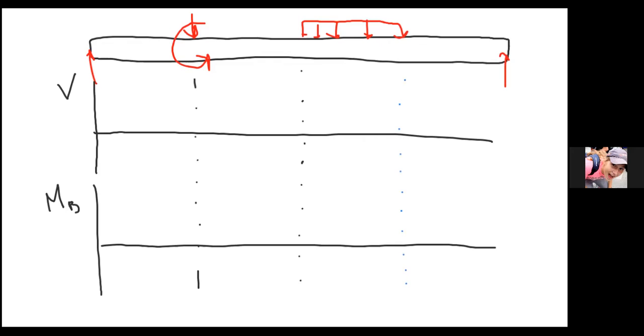So for shear force, these are a lot easier to tell just by looking at the graph. So here's more or less how you can think. If I start at this end right here, I'm basically going to add this AY and get bumped up to there. And then the entire time I go over to here, nothing's changing, right? So I start at what AY is, which is 4750.